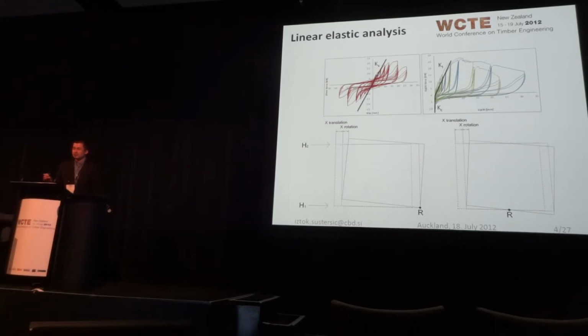However, if we're dealing with torsion, or with higher vibration modes of higher buildings, displacement-based design also has to be corrected with correction factors that come from the modal response analysis. So let's not underestimate the power or the influence of the modal response analysis, which is actually not as simple as it may seem at first glance for cross-lam.